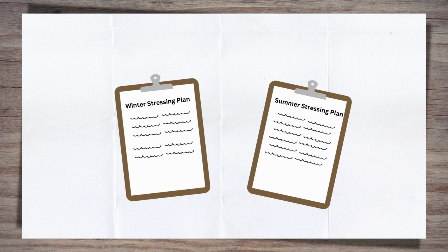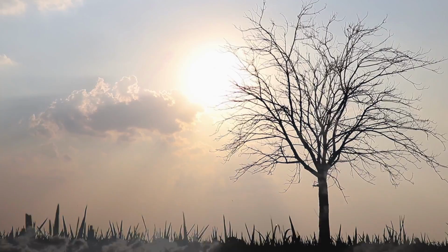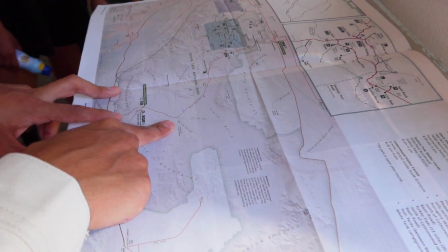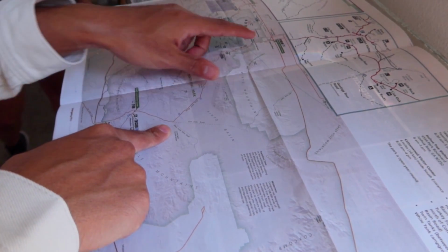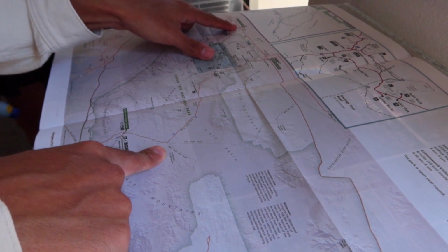Some countries and areas have such an issue with the temperature ranges that they experience that they undertake a programme of stressing, both at the end of winter to prepare for summer, and then again at the end of summer to prepare for winter. Given that the change in climate means we're experiencing higher summer and lower winter temperatures, it's likely that well-established SFT values will have to be adjusted, or seasonal adjustments may become the norm for everybody.